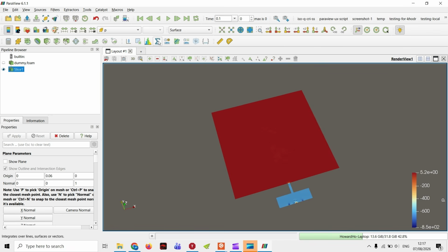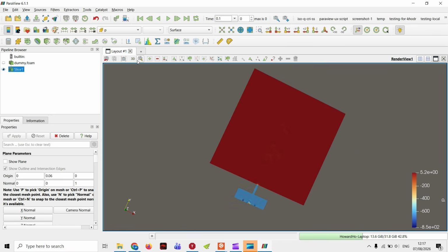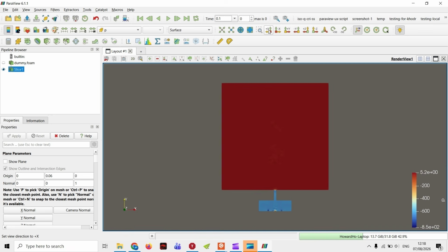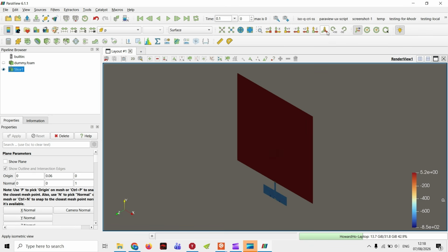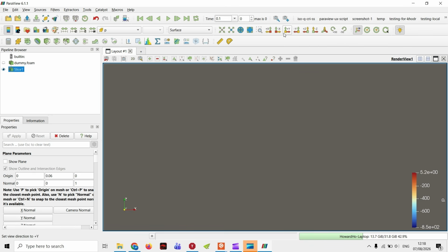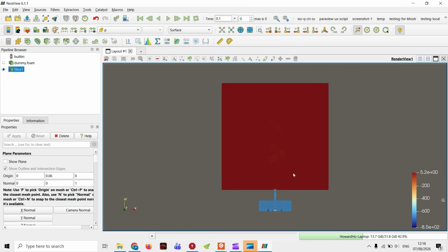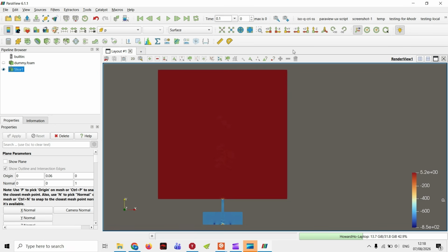Now, so far we're relying on the 3D field. You can press this button to switch to 2D, and then usually when you switch from 3D to 2D, it kind of changes the angle a little bit. So if you're trying to output a screenshot, you almost want to always align it in 2D first. And then I should mention these buttons are going to be your best friends. These are basically automatic set orientations for the camera. Isometric and Z or XY, depending on geometry, would be the easiest, the fastest way.